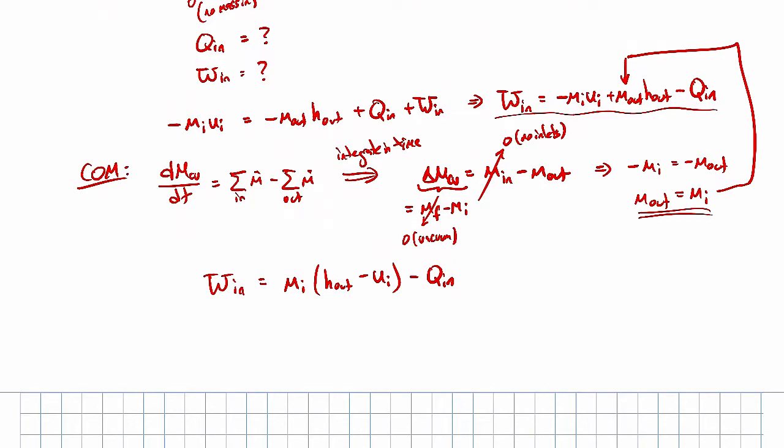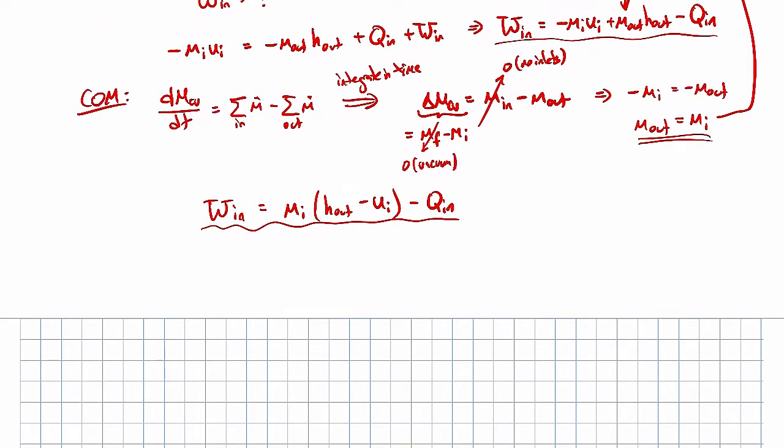Let me now, okay, so I'm going to underline that so we remember it. So now, again, I can find the initial mass from the ideal gas law. Let me write that down. So the ideal gas law applied to the tank: the initial mass will be the initial pressure times the tank volume divided by the gas constant for air divided by the initial air temperature inside the tank. So we can find the initial mass through that. So that's not going to be a problem.